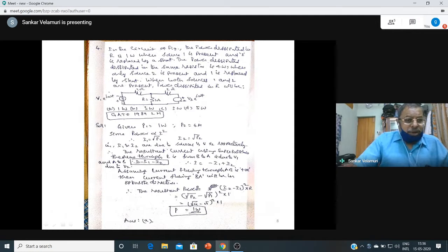So there is a voltage source here. Although we used to say if both polarities are given, minus and plus, it is a DC source, here it is given as V1 e power j omega t. It is a complex wave. E power j omega t is cos omega t plus j sin omega t, so it is a combination of the sine and the cosine. Right?